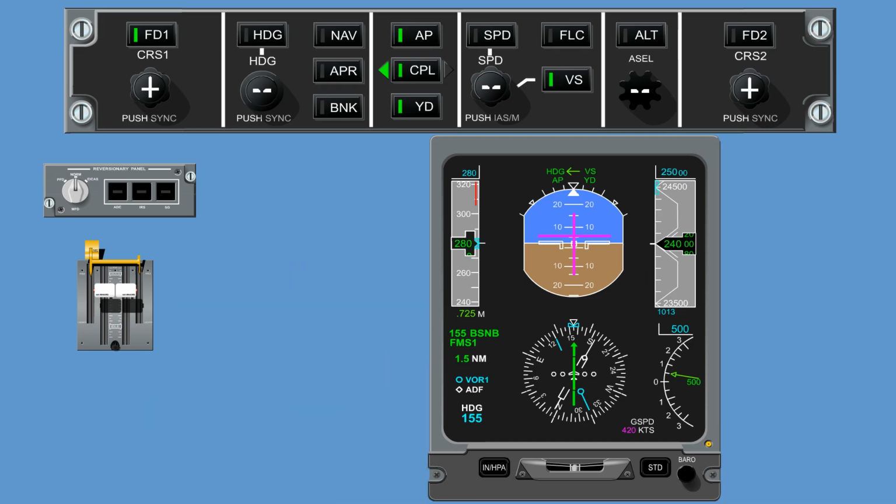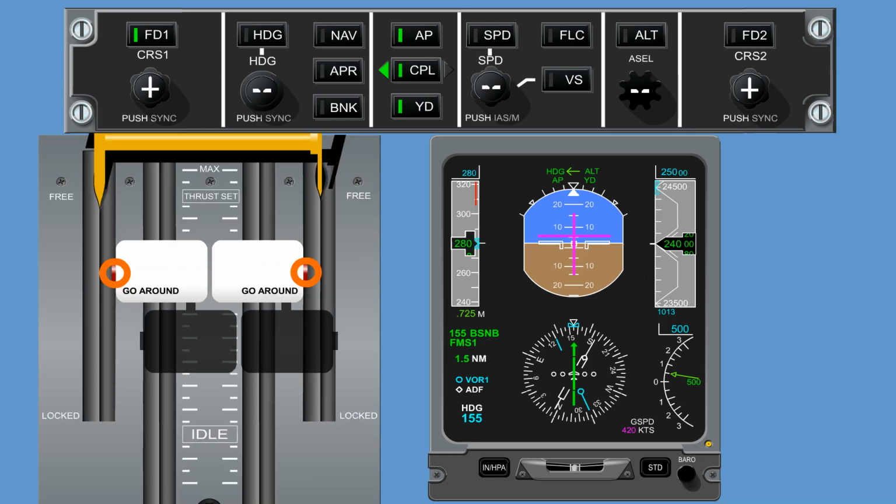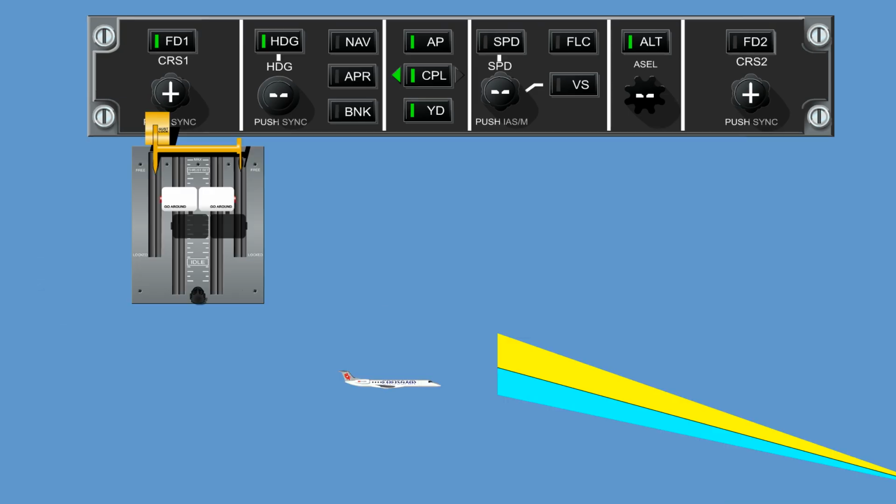The vertical speed mode can be cancelled by either pushing the vertical speed, flight level change, or speed button, by coupling to the cross-side flight director, by changing the symbol generator driving the primary flight display, or by selecting Go Around. The glide slope mode allows automatic capture and tracking to glide slope transmitter signal.